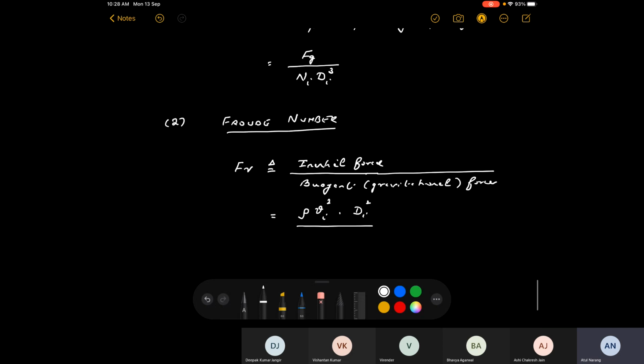In contrast, the stress created by gravity is essentially rho times g times d sub I. This is, if you remember the formula rho g h, the pressure at a particular point. I mean, pressure has units of stress, so you can think of this as the force per unit area created by gravity. And of course, this also must be multiplied by some measure of the area, which I have taken to be di squared.